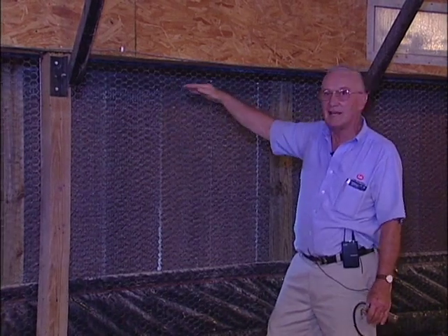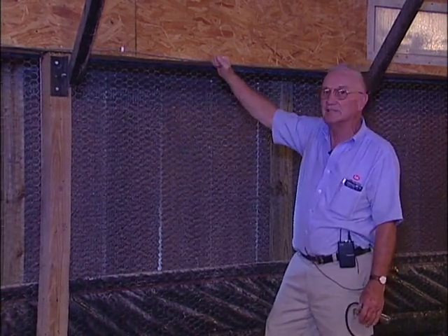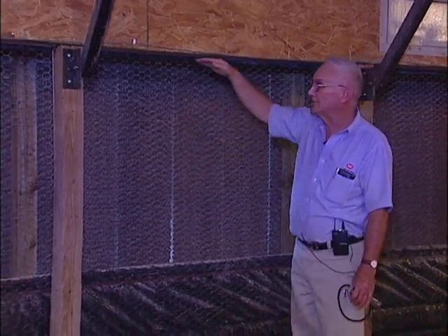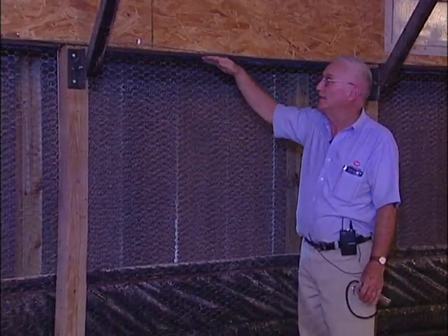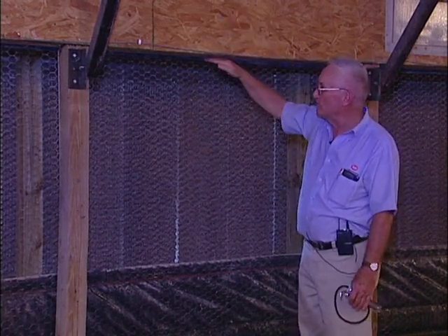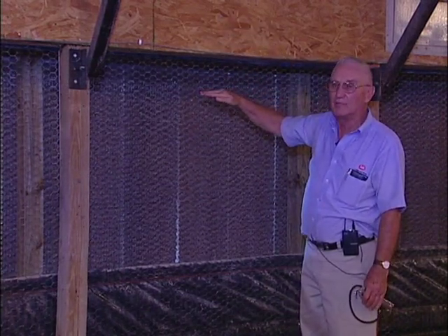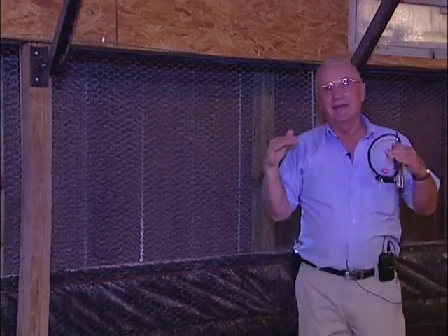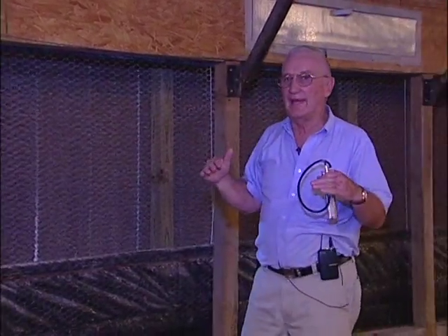Now, also on your inlet opening, the top of your inlet opening entering your house shouldn't be any different from the top of your pads. We don't want this opening to be above the top of the pads. So in this case, they're even. If this was higher, what we would do is add a permanent curtain at the top to get the inlet opening down even with the top of the pads.